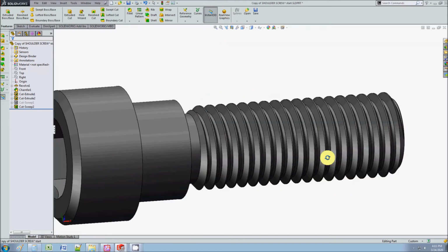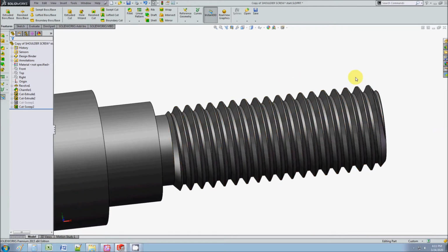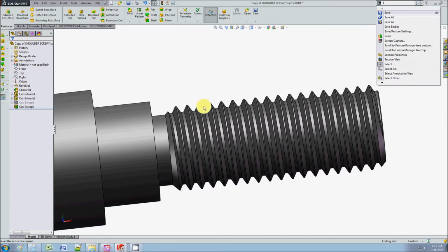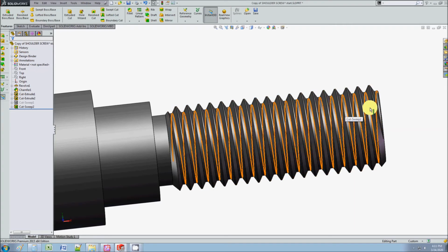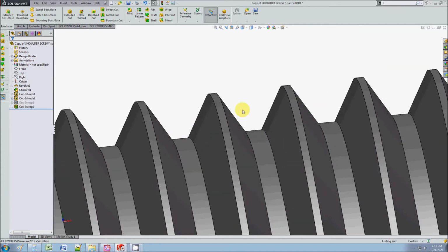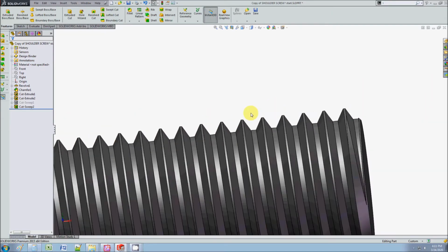So this is a very standard 3/4 inch thread. If I go to Home Depot and buy a 3/4 inch thread, this is what you get. This is the exact size. There is a threading tool. Okay, no, it's not this. It's a relatively new tool. It's called Threads, and it actually generates what I created here. But the thing I don't like about the Threads tool is that it doesn't let you customize it. It doesn't let you really get the amount of control that I have over some of these little details.